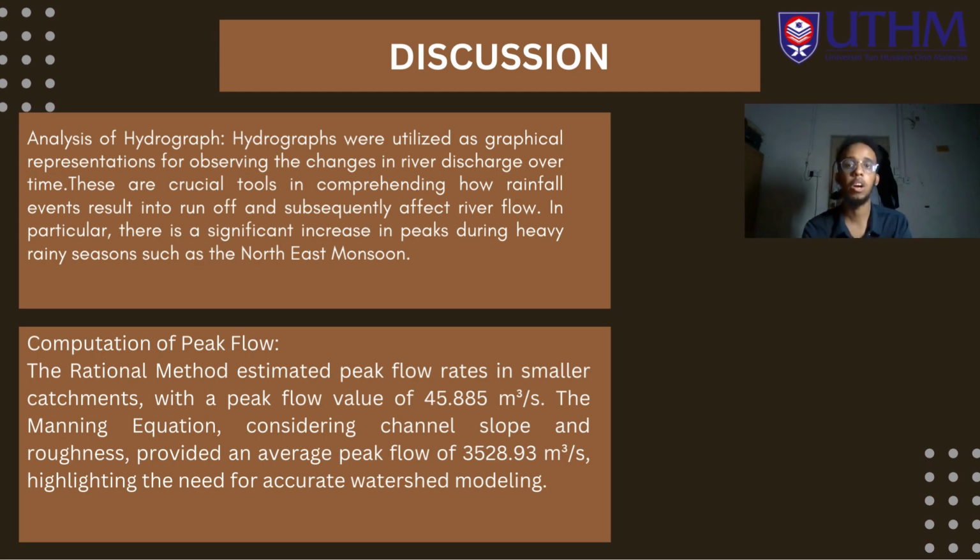Analysis of hydrograph. Hydrographs were utilized as a graphical representation for observing the changes in river discharge over time. These are crucial tools in comprehending how rainfall events result in runoff and subsequently affect river flow. In particular, there is a significant increase in peak during heavy rain seasons such as the northeast monsoon.